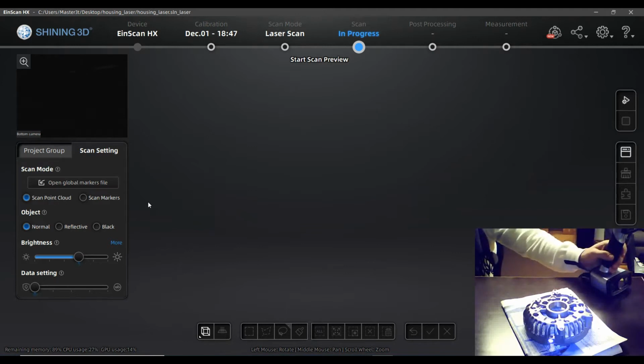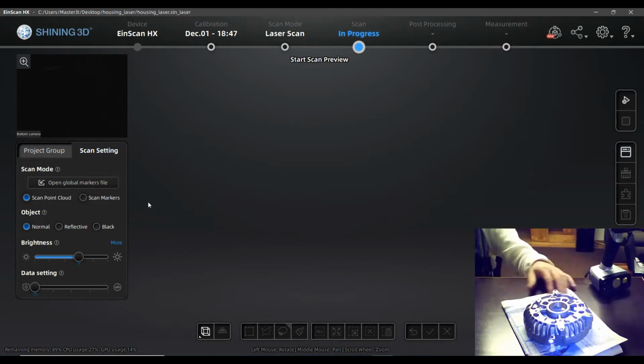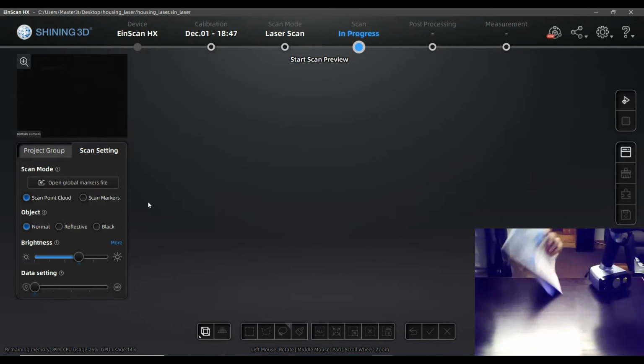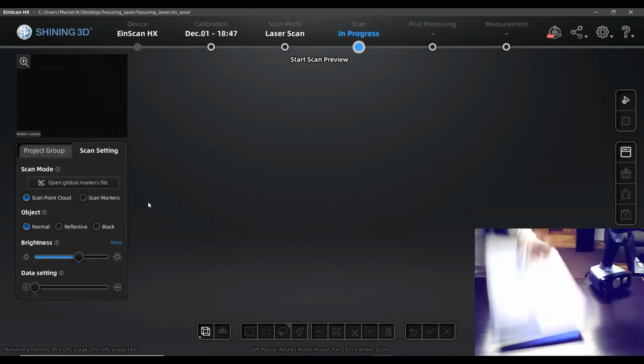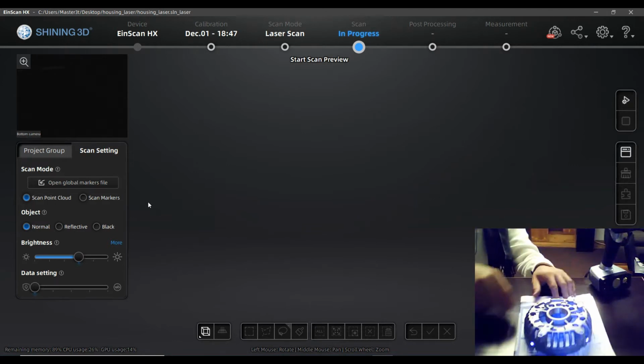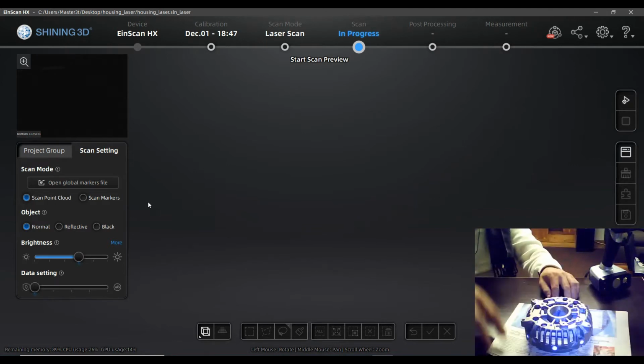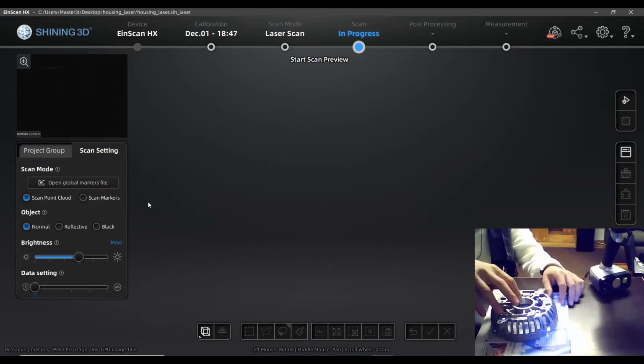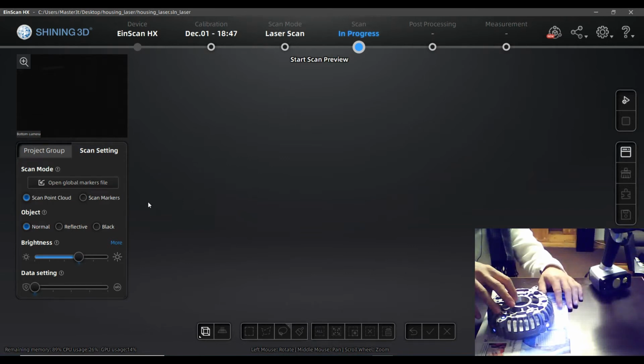I recommend having in the field of view of the scanner a minimum of 4, better 5 markers. And as we already prepared that part, we can start. I just wanted to use a turntable today, but unfortunately I left it in the laboratory, so I'm going to make it somehow different. You can use newspapers, of course, turning them on some flat surface. You probably have a problem merging scans that use the surface of the newspaper as well if you don't cut it away.